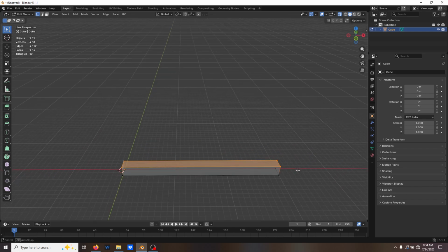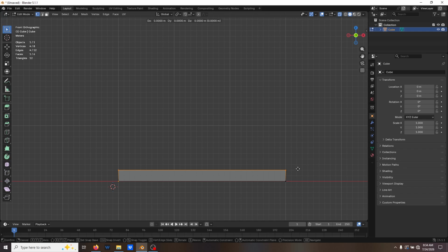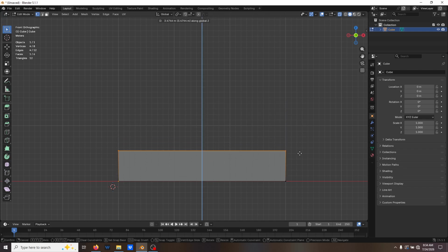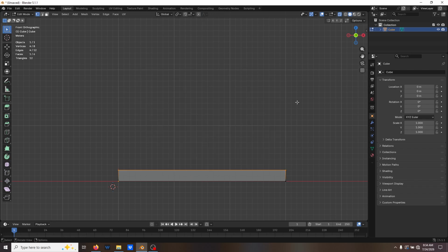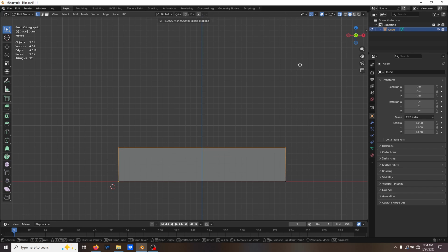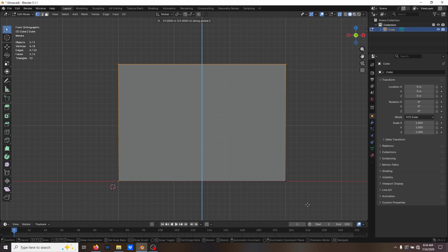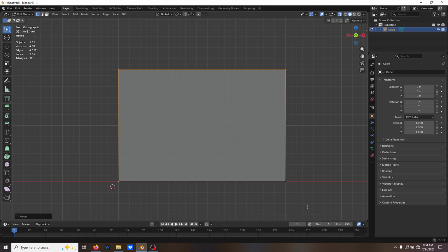Now I can also grab these vertices and press grab and then Z. You'll see it'll go loosely here, but if I hold Control, I can snap while doing this. So you can turn that on and off. Oops, screwed that up. Let's see, grab Z. Now I can also use the numbers as well, but I'm just going to drag this time. There we go. And boom.